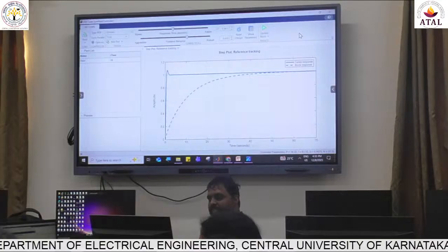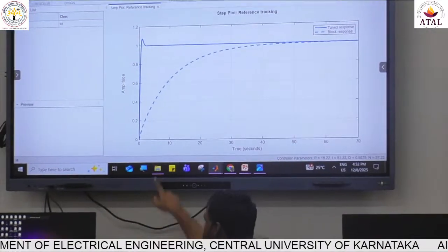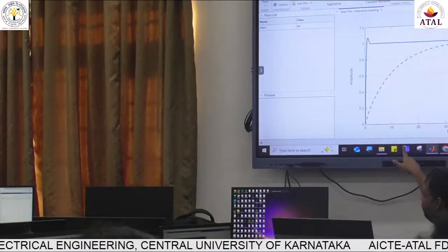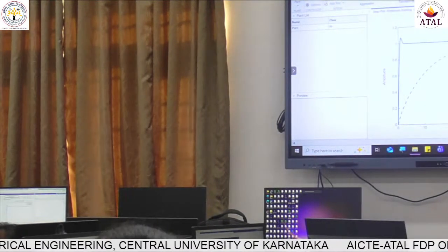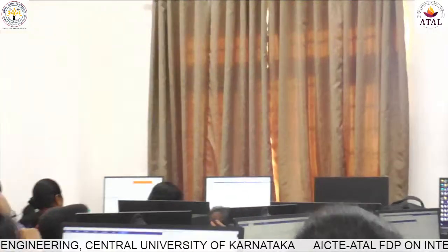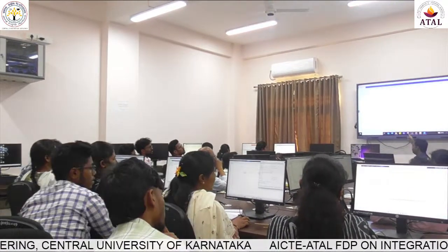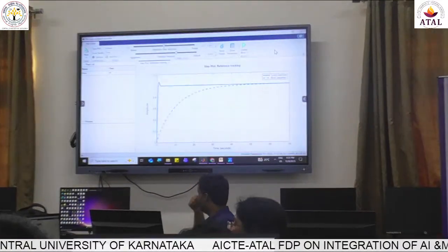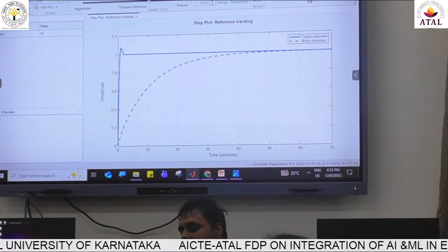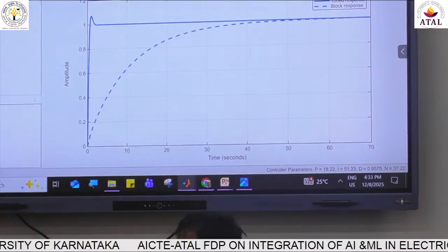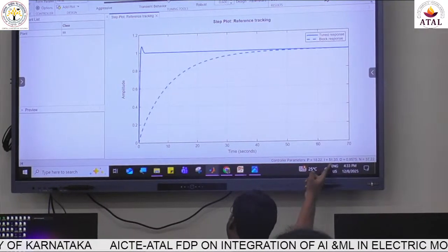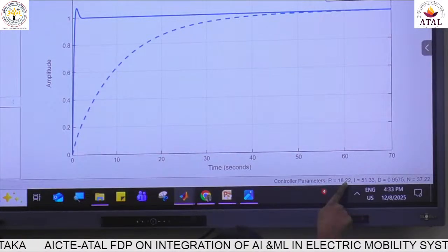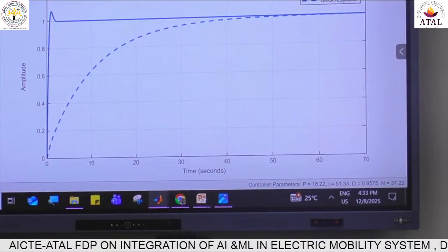If your system has any instability, you should see a message here saying that for a certain level of tuning we were able to identify unstable output, so we are ignoring those conditions. Right now there is no message, which means no instability was found by my tuner. So we have stable internal parameters; the motor parameters you have taken are stable. And right now we can see at the bottom that my tuner has been able to optimize the PID values.